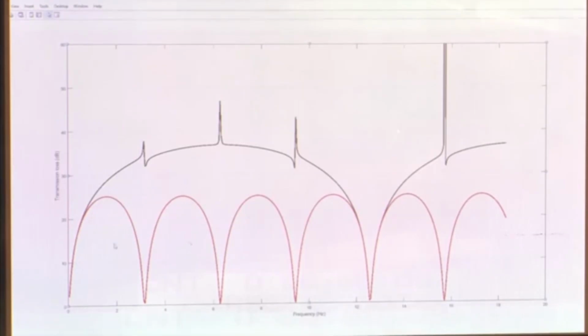Overall, this kind of broadband hump is seen, which basically almost guarantees you 20 to 22 dB of transmission loss from a range as low as say K naught L equal to 0.1 or 0.2 all the way up to K naught L equal to maybe 11 or something like that. That is roughly from 100 hertz to about maybe 1500 hertz or 1400 hertz or so on. So, it is pretty impressive.